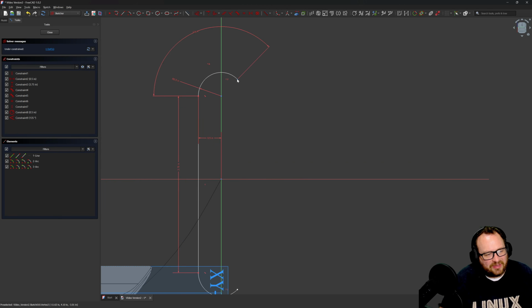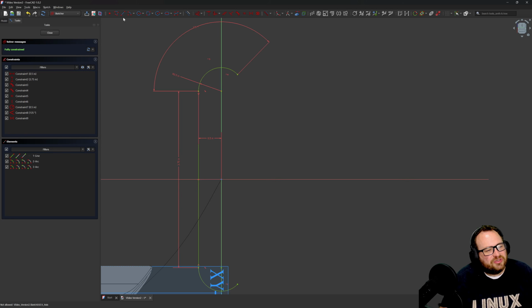Now what is not constrained? So I'll click and drag, and it looks like we need to be symmetric. So I'm going to hit S for symmetry. We're going to go line end, the other line end. We're going to make that line symmetric right around that origin. Again, hit S, click point, point, and then your axis of symmetry, and your line will snap symmetric. We'll switch to